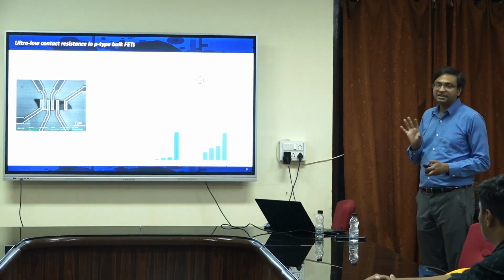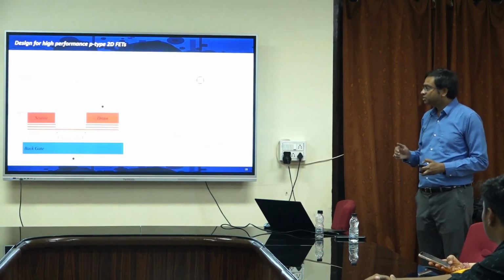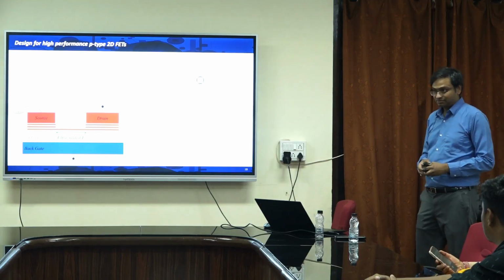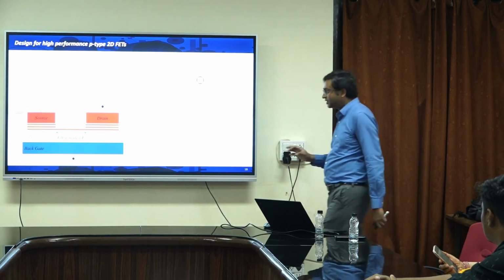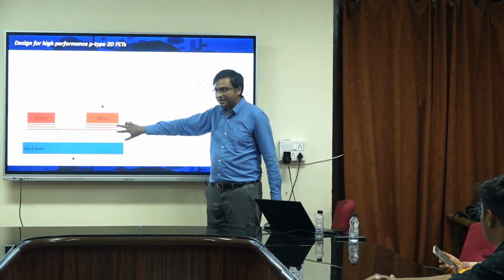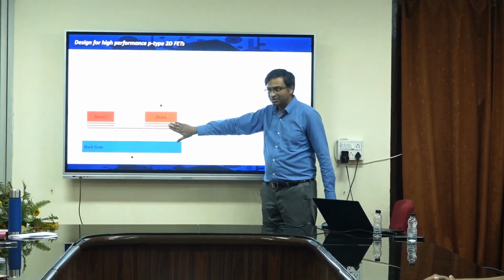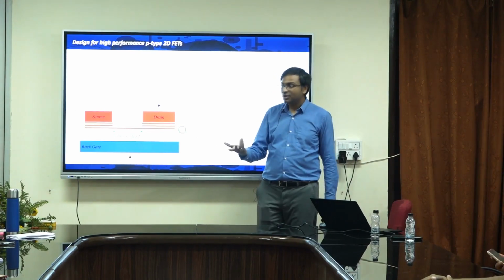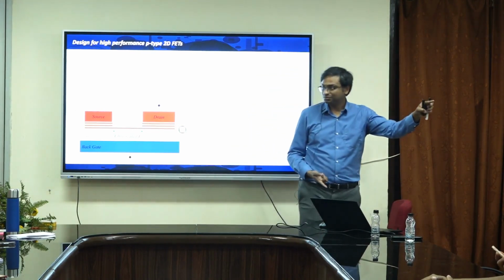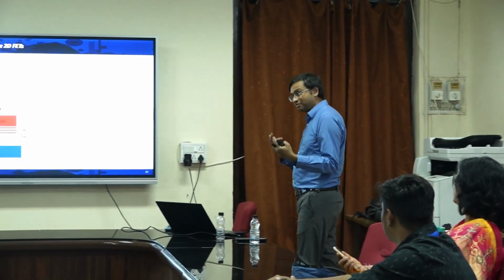So therefore, if I think about envisioning a device structure which will give me both, shouldn't it look like this? What I should have is a thicker contact material, which is thick under the contact, because then it will be degenerately doped, right? While the channel should be thin, because that will give me gate control, right? So that way we can achieve the best of both worlds.